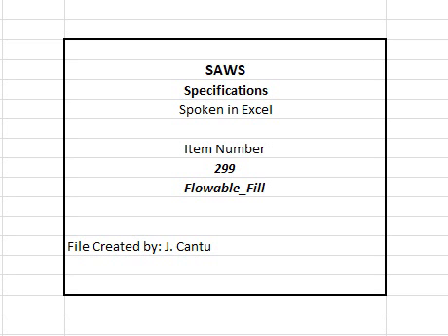299.5 Construction. Unless otherwise shown on the plans, furnish a mix meeting the requirements of this section as set forth below. 1. Strength. The compressive strength range shall be between the following strength values unless otherwise directed by the engineer or shown on the plans. A. Low strength. Between 80 psi and 150 psi at 28 days. B. High strength. Greater than 500 psi at 28 days. For emergency repairs, strength shall be greater than 50 psi at 2 hours.